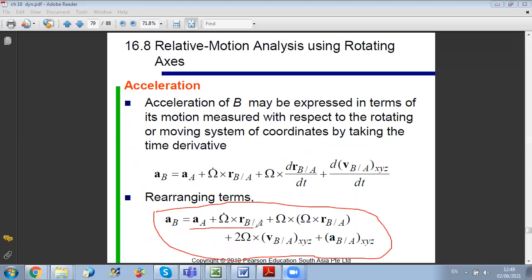It is the point of the rigid body on which C is located at this instant. This is rod OC, and C now is on this point of the rod. So the rod will give the velocity of this point and acceleration to the collar, plus we should account for the relative motion of the collar with respect to the rod.